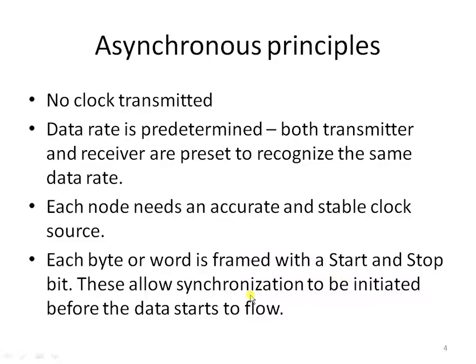The complete message bits will undergo one process, and that process is called framing. The output of the framing process is termed a frame, and inside the frame we have the message bits along with start and stop bits, as well as one optional parity bit added to the original message bits. Let us see how it looks.